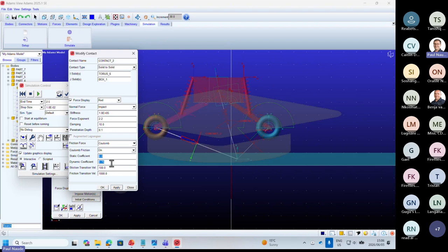It actually makes for a nice demo if you want to show a student why old cars don't have disc brakes at the back, but have drum brakes at the back and disc brakes at the front. And it actually has to do with this phenomenon that your static coefficient is higher than the dynamic coefficient.